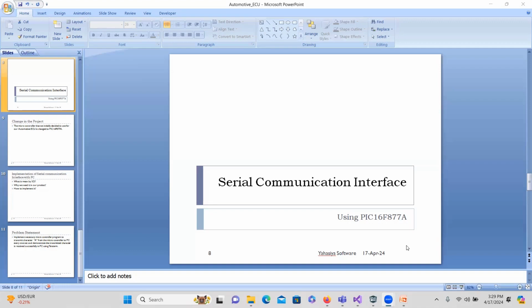So our aim is to make a serial communication bootloader in our microcontroller, that means in our product. Later we will use this serial communication to flash our executable to the microcontroller. That is very easy when the code becomes very big. At that time, we should not have to remove the microcontroller from the motherboard every time. So that is the aim.